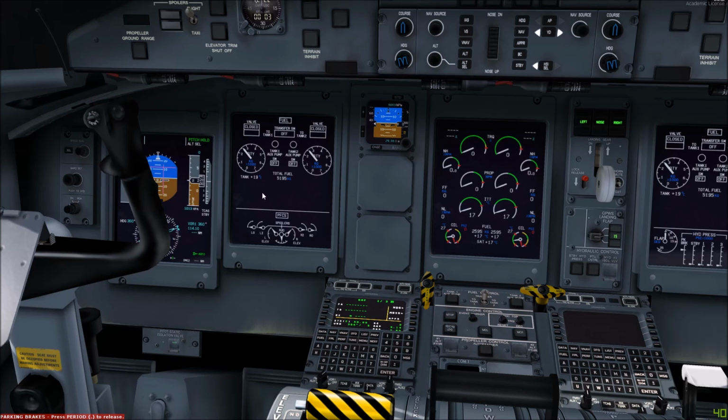Fuel is fed to the engines usually via an ejector pump to an engine-driven pump, or via an auxiliary AC electrical pump. The master switch can be found here on the center panel. The auxiliary pumps generally aren't used in flight, but are used prior to departure and also for the approach as a backup for the fuel system.